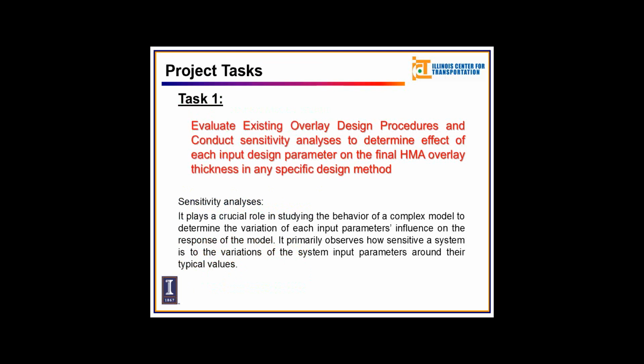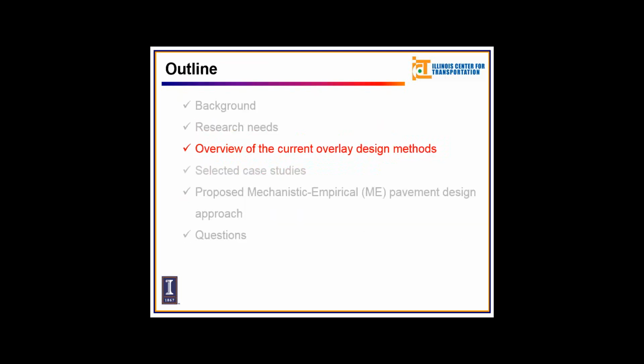So the first task was to evaluate the existing overlay design procedures and conduct a sensitivity analysis to determine the effect of each input design parameter on the final overlay thickness in any specific design method. What the sensitivity analysis does is basically study the behavior of a complex model to determine the variation of each input parameter's influence on the response of the model. It primarily observes how sensitive a system is to the variation of the system parameters around their typical values.